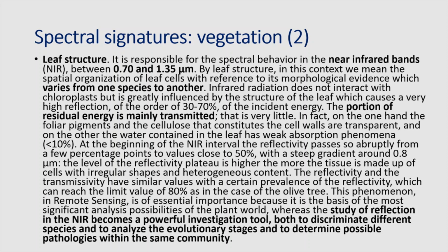This phenomenon in remote sensing is of essential importance because it is the basis of the most significant analysis possibility of the plant world, whereas the study of reflection in the near infrared becomes a powerful investigation tool both to discriminate different species and to analyze the evolutionary stages and to determine possible pathologies within the same community.